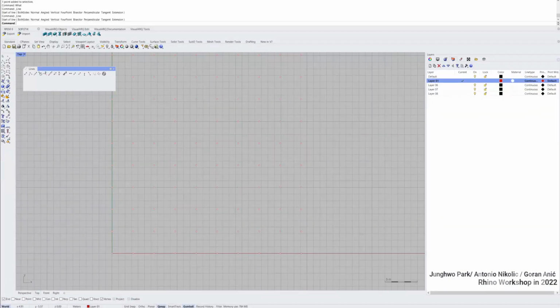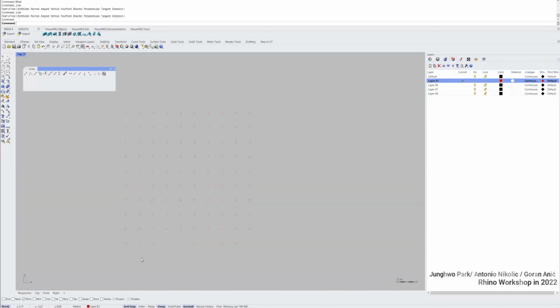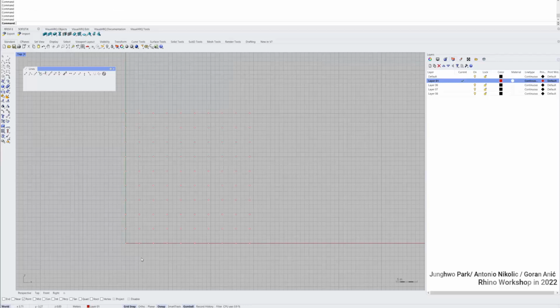Then you can see it's bold text, and you can now choose near or end point. You can snap to point, middle, or center, and so on. There are a lot of options. For now let me select point, and I'm also going to enable grid snap. The grid is the background behind. You can press F7 to turn it on and off.